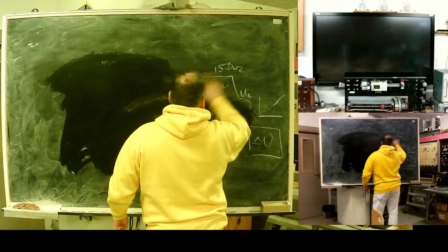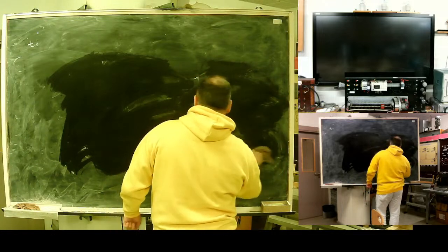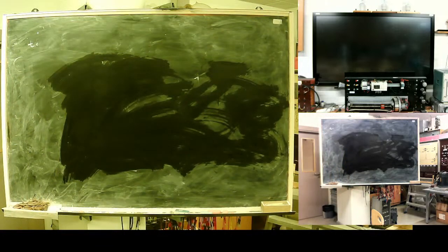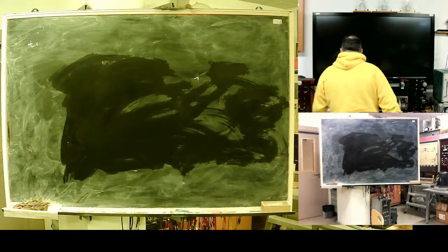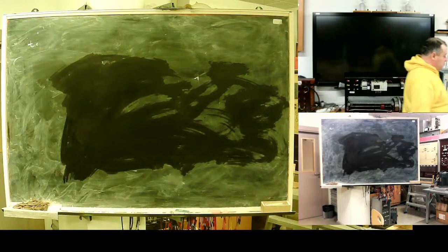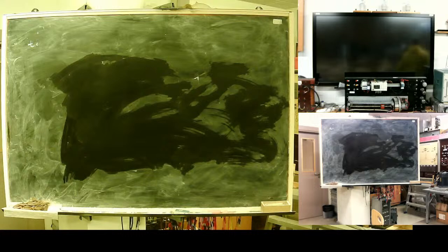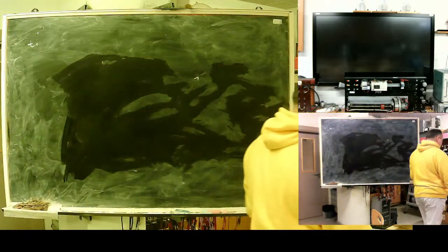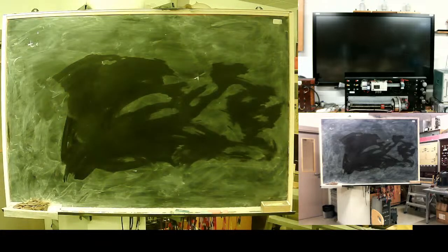What's the idea? See, generator voltage contains third harmonic. No one bothers about it, because in the schematic of isolated neutral, third harmonic current cannot circulate in the transformer winding because it's delta connected. So there will be no voltage disturbance at the customer.